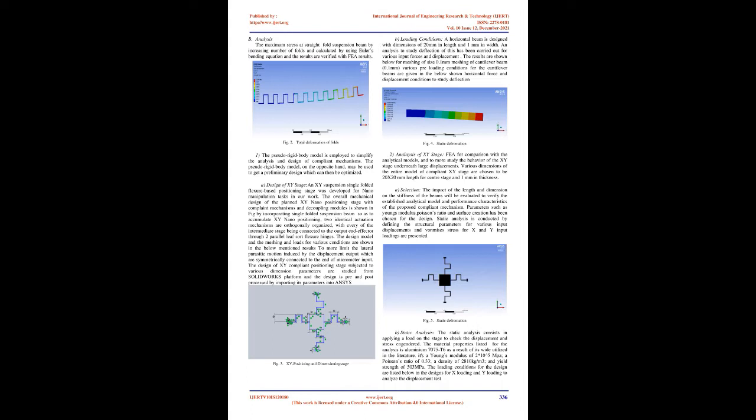1. The pseudo-rigid body model is employed to simplify the analysis and design of compliant mechanisms. The pseudo-rigid body model, on the other hand, may be used to get a preliminary design which can then be optimized. A. Design of XY stage and XY suspension. A single folded flexure-based positioning stage was developed for nano manipulation tasks in our work. The overall mechanical design of the planned XY nano positioning stage with compliant mechanisms and decoupling modules is shown in the figure, incorporating single folded suspension beams so as to achieve XY nano positioning.